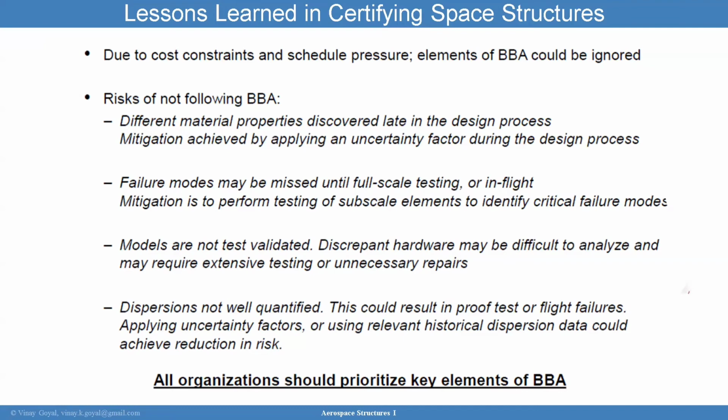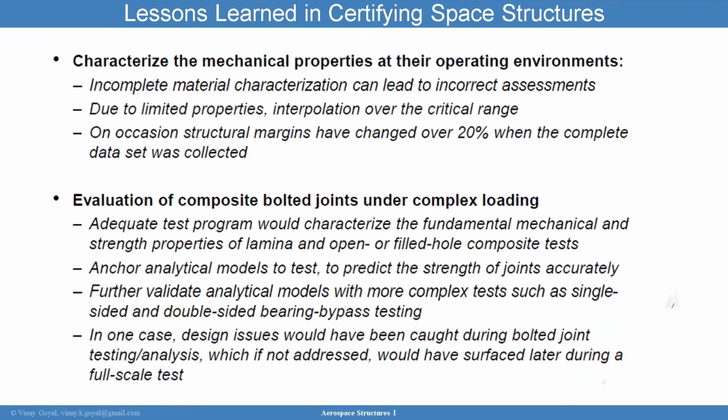So if the dispersions are not well quantified either on the loads or characterization side of the material, then you could be potentially facing a proof test failure or flight failure. So applying uncertainty factors or using historical dispersion data could help here. It could reduce the risk.